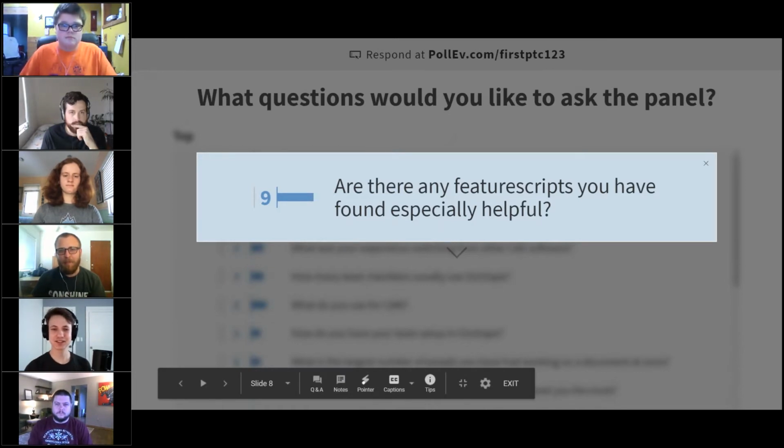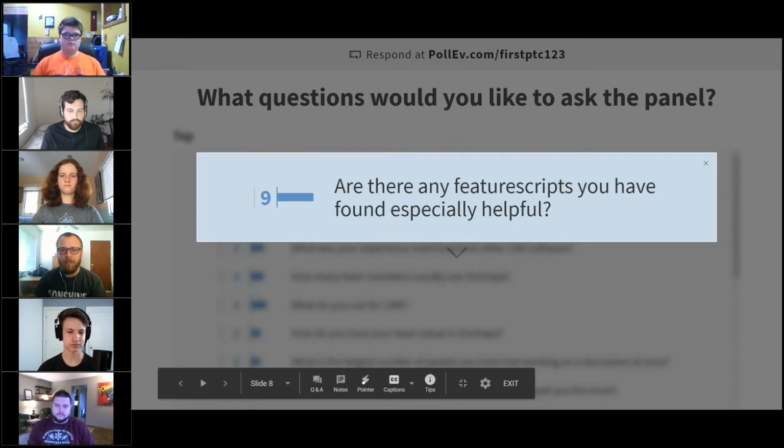Yeah, so we were talking before the show, but we're working on a couple of off-season robot designs right now. And there's been a couple really great feature scripts that we've come across since the start of the off-season. A first community member, Julia, has produced a couple of really awesome feature scripts. We've been heavily using the tube converter feature script that they created, where it basically takes a solid model of a 2x1 extruded solid, or a 1x1 extruded solid, or a 2x2 extruded solid, and applies our standard hole pattern. And there's even a 1678 mode in the feature script, which is really convenient for our students to know which one to use, which is pretty great.